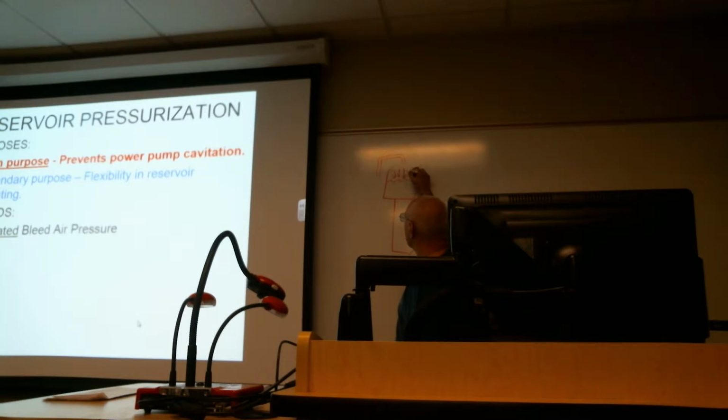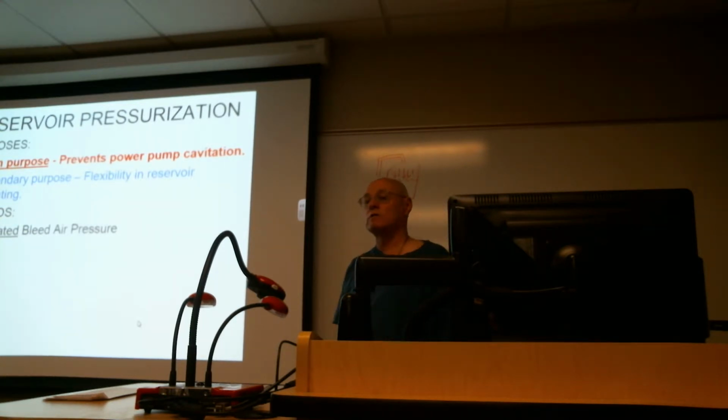And this works just well and fine at sea level. You've got the column height of liquid that is also aiding in delivering fluid flow to the pump, but you've primarily got also atmospheric air that's pushing on the fluid. But how about if we were talking about an aircraft that's got a reservoir for the hydraulic system and we're flying at altitude? You don't have the same amount of air pressure pushing on that liquid. You need some kind of assistive aid.